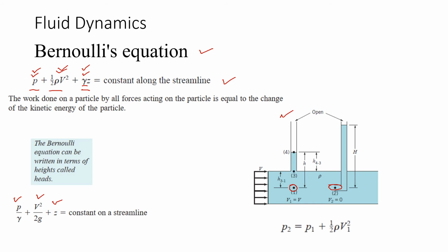So for this scenario, what we did, we found the total pressure P2. Here you can see that this is the pitot tube arrangement. If you remember, the pitot tube is used to find the velocity of jets, and P2 right here is a point where we will measure the total pressure.